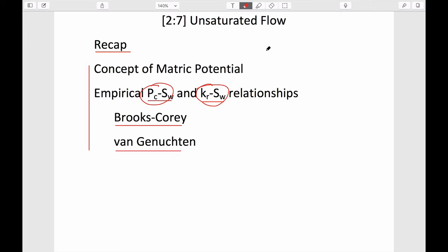We noted that the value of head is equal to elevation, plus fluid pressure divided by unit weight of the fluid, plus v squared over 2g. I guess we know that in a fluid, relative to some datum where z is equal to 0, then choose a point.